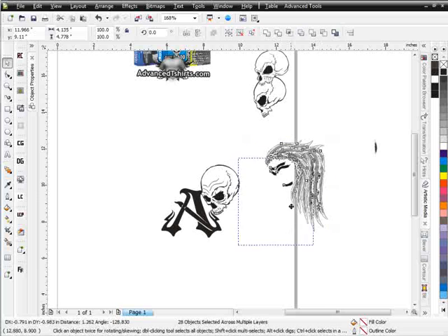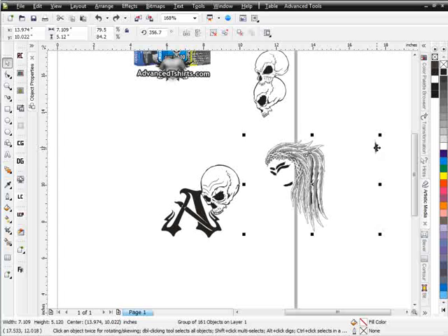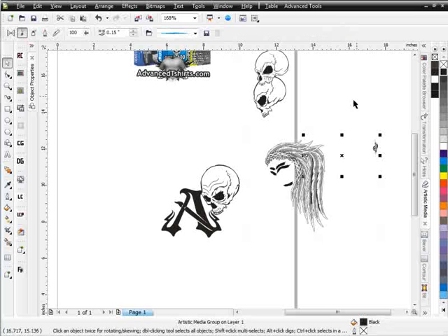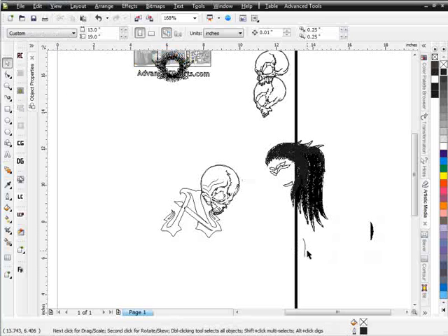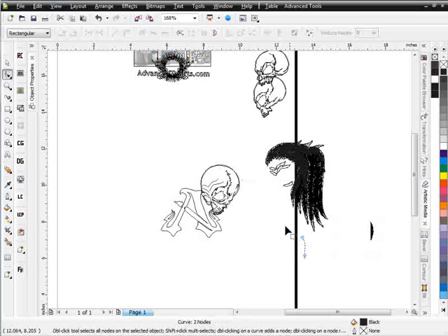I'm going to select everything here. And I think I might have missed a few objects here. Let's see if there's some objects set up on wireframes or not. I'll take this here. I'm going to move all of this. This here I'll ungroup. Select Ungroup All. Now this is hooked up to something here. It's probably hooked up to a wireframe. If I go to View Wireframe, take a look, yes it is. So what I want to do is just go ahead and select these two wireframes and delete that, and we won't have to deal with that anymore.